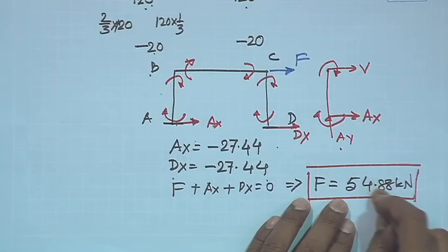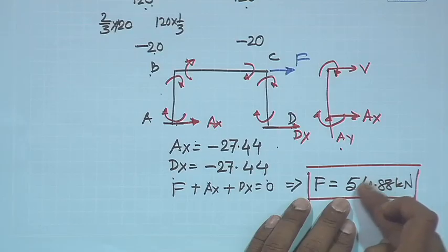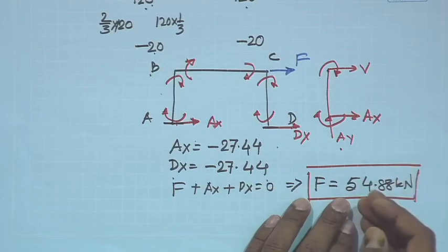So, the delta sway is caused due to this amount of force. The 100 by EI sway that we started with is caused because of this amount of force. Instead of 100 by EI, if you take 50 by EI, 25 by EI or 330 by EI, then you get a different F value, but that F value will be consistent with the delta that you take.